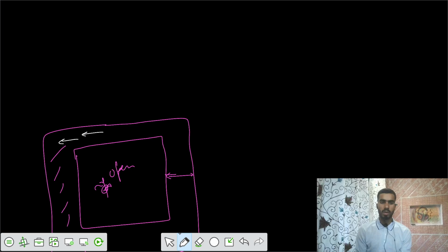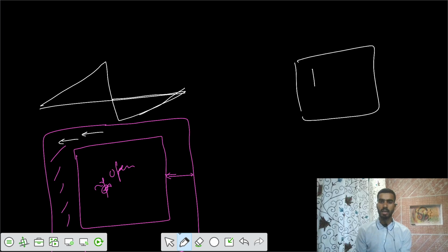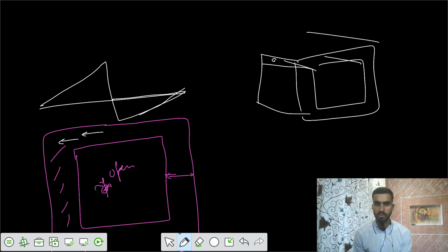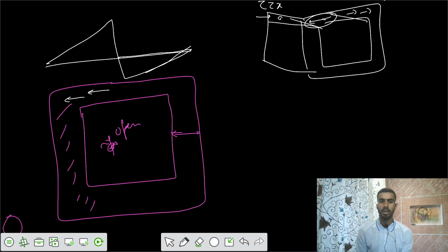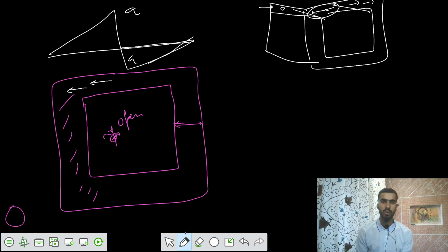Because your shear flow would be in this way. We know the shear flow variation would be in this way, based on the fact that when you took that differential element, you said there is some unbalanced horizontal force, then there came the tau xz. Similarly, you can have tau zx from the other side. So there would be some shear flow q again, and similarly you can have it in this way also.